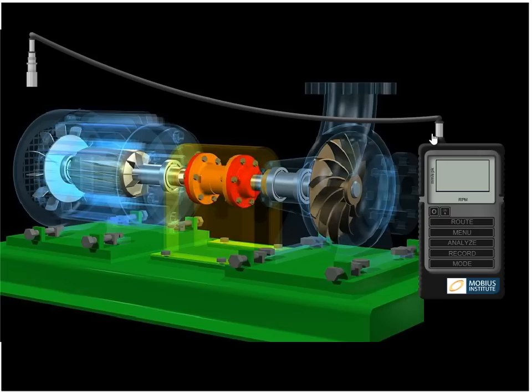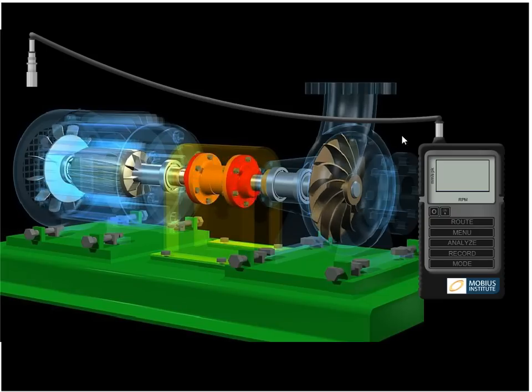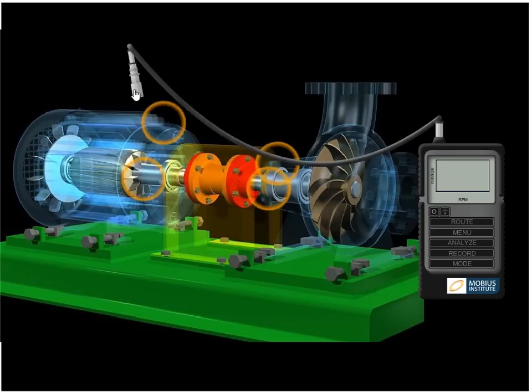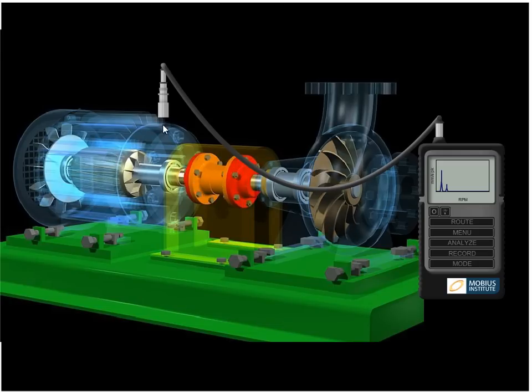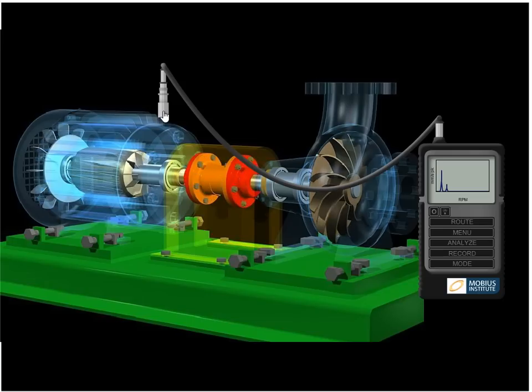Okay, so the way we do this is, as you've just seen, we can put the vibration sensor up there on the bearing, and all the vibration is transmitted through the machine itself up to that point. The sensor has to be mounted properly. That is very important, so that all those high and low frequencies get up into that sensor.